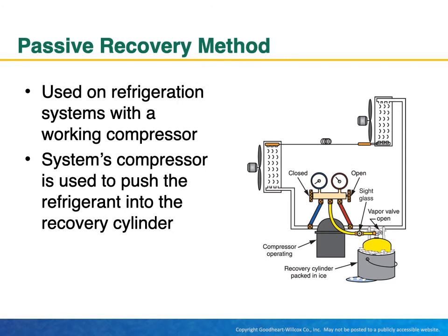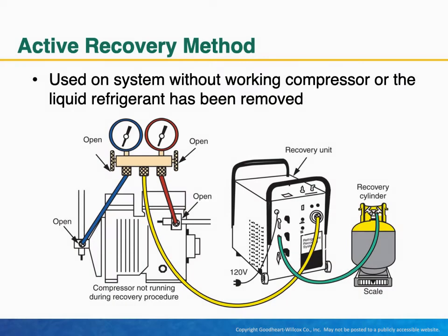Passive recovery method. Used on refrigeration systems with a working compressor. System's compressor is used to push the refrigerant into the recovery cylinder. Active recovery method. Used on systems without working compressor or the liquid refrigerant has been removed.